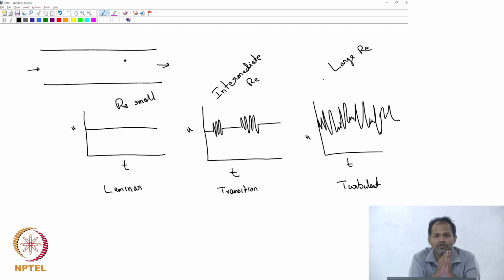So what we have done so far, let's say we calculated the pressure drop in a pipe. We derived nice relations, but all those are useful when the flow is laminar, but not when it is turbulent. So there's a clear distinction. You can see that visually, but mathematically also that's going to be a distinction, and therefore we need to know what the velocity profile in a pipe is when the fluid flow is turbulent. Our objective now is to derive an expression for that, so that we can calculate the pressure drop and come up with the right pump, so that you can pump fluids.